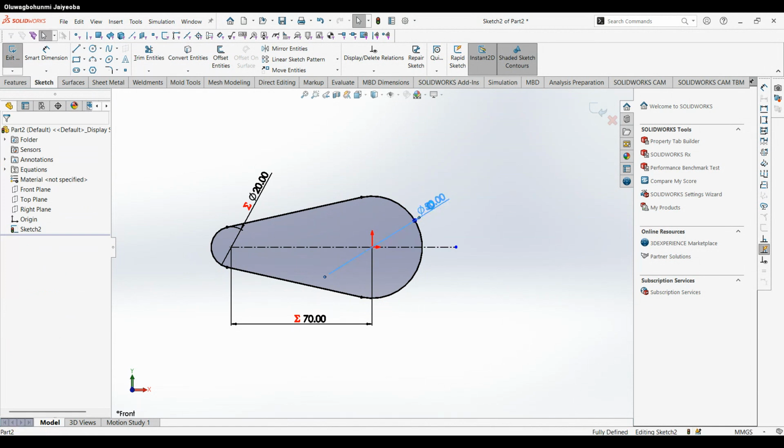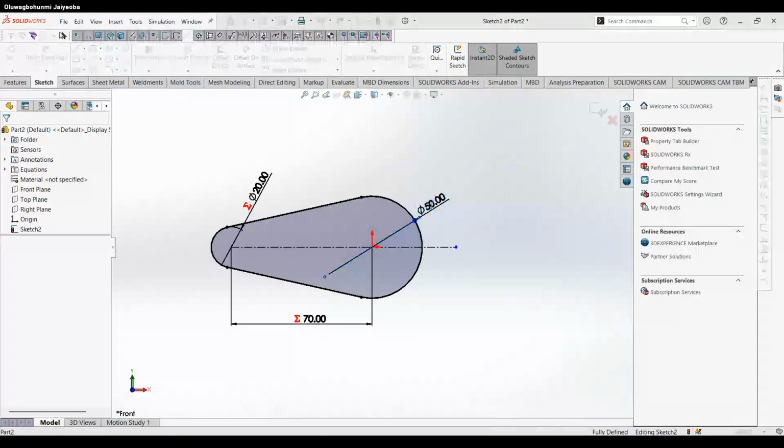So that when I get my next question and they ask for a different value for my variable, let's say variable A was 20, then I go to question 2, and question 2 says variable A should be 30. If variable A is 30, I don't need to start dimensioning all over again. If I have my parametric equation set already, it automatically updates the model to the new value of the variable.